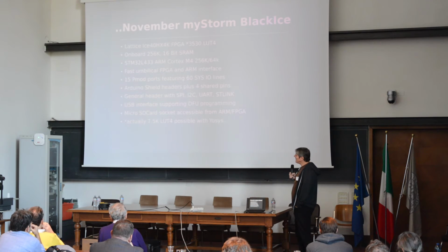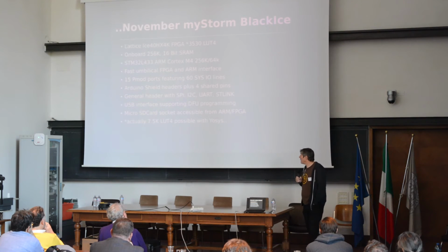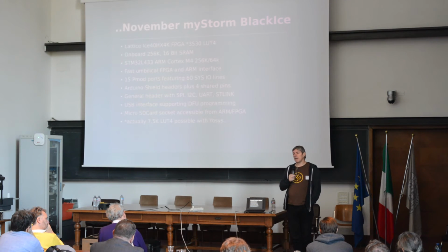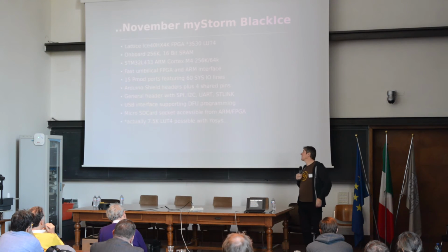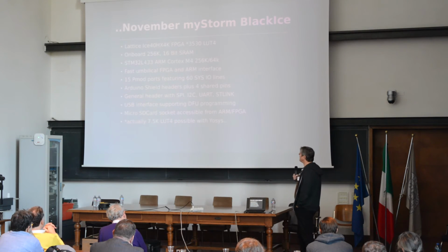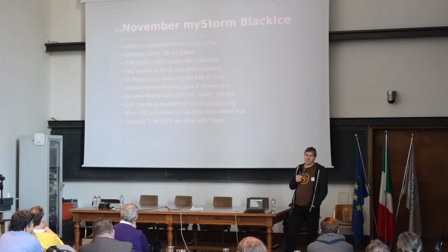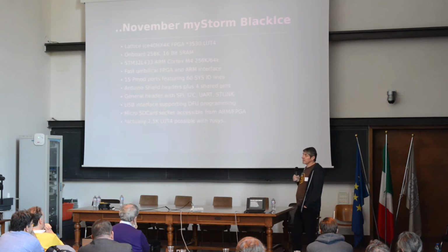What we have changed is we are using the STM32L4 ARM Cortex M4. Initially we were looking at using the Chinese GDF32, which gives us very good memory in terms of flash size, but it's not as high performance, and we also have some issues doing the drivers for it. Going this route, we get a very reasonably priced ARM that has a number of benefits, including the fact that it's got the M4, so it has a floating point coprocessor in there. But it also has lots of flash, 256K, as well as 64K of RAM.